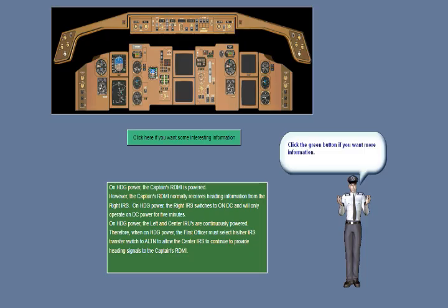An external power receptacle on the right side of the airplane just after the nose gear allows connection of an external electrical power source. Although both APU and external power connect to the bus tie, only one can be on the bus tie at a time. Paralleling of power sources is not possible. An illuminated available light in the external power switch indicates that the external power generator is producing acceptable AC electrical power.